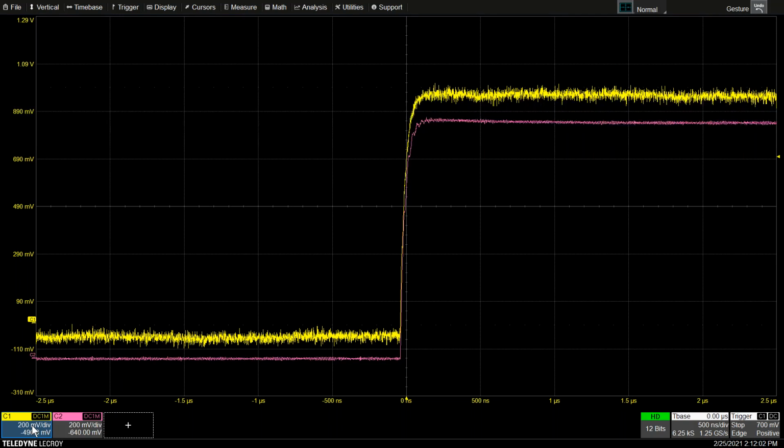Look at the amplitude noise we're now seeing on this. We've just taken our 12-bit scope and made it a 10-bit scope. Because if we have 4,000 quantization levels from the bottom to the top, each division's 500 quantization levels. But if we're only using a fourth of it, that 4,000 becomes 1,000 that we're defining the acquisition of channel 1 on. So now 2 to the 10th makes it a 10-bit scope.